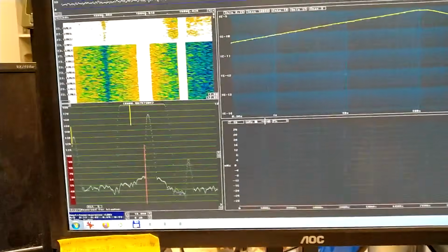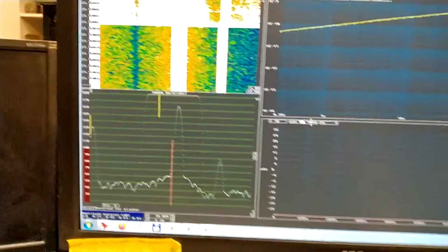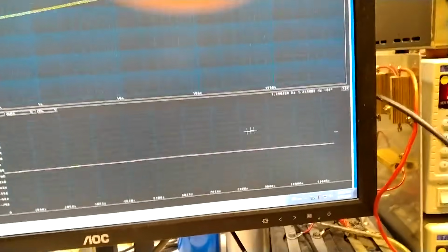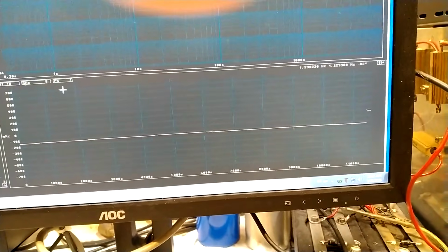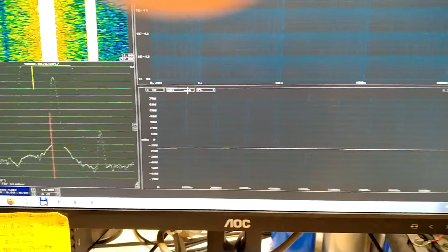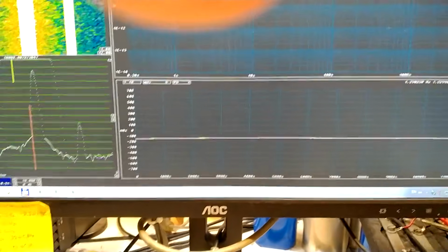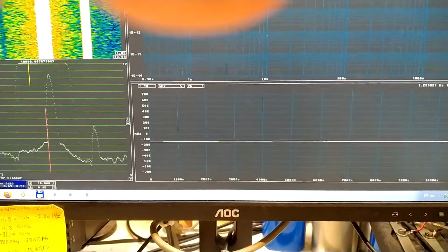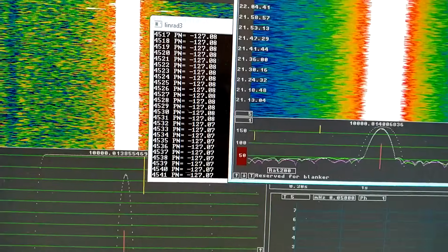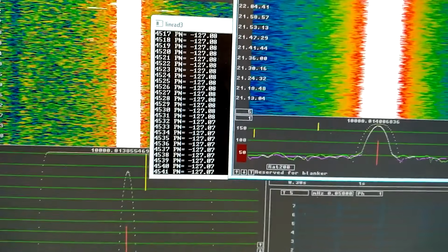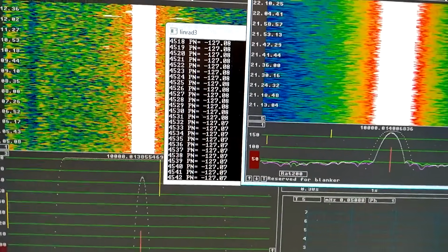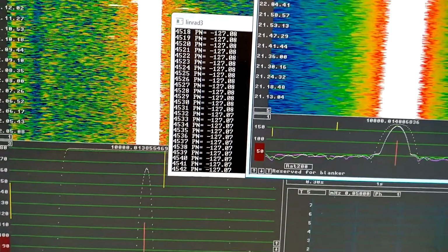And the frequency jump is large. Here, with the very high scale number 5, I can see the jump here, which is about 200 millihertz, 0.2 hertz. The average noise has declined by about 3 decibels. It was minus 130 at best.